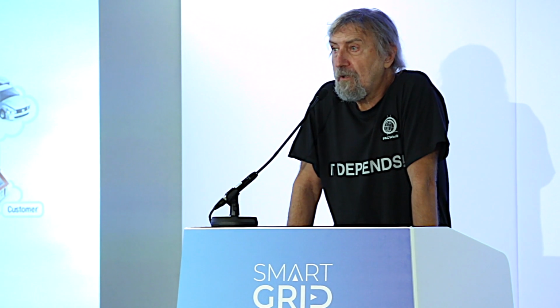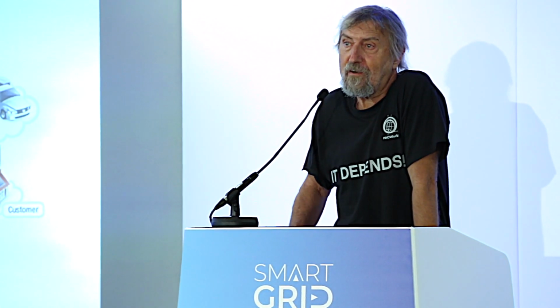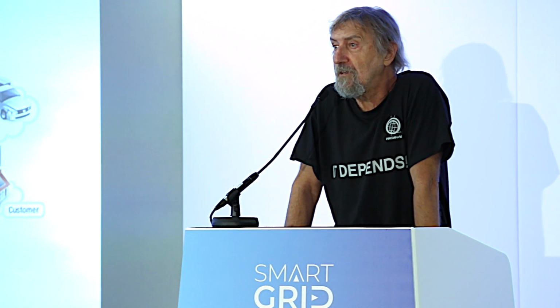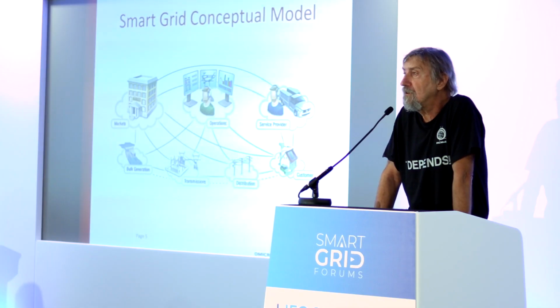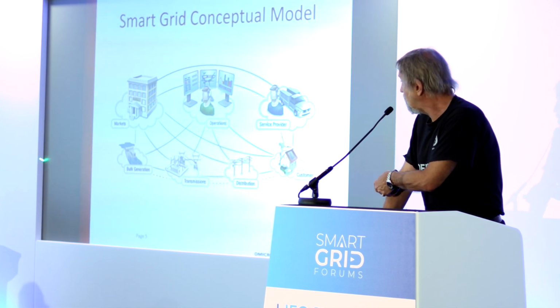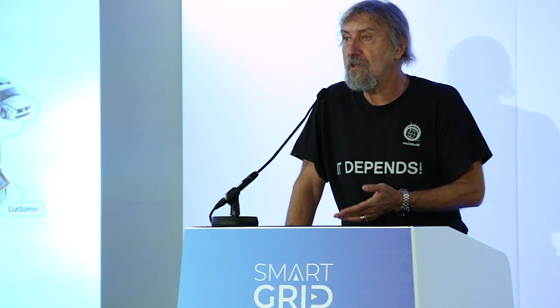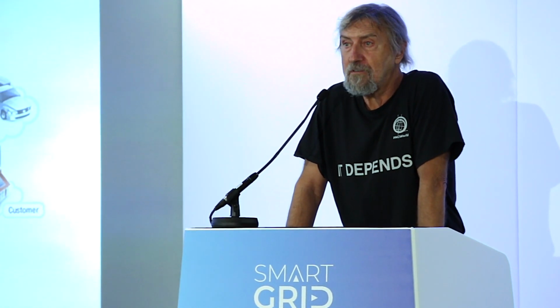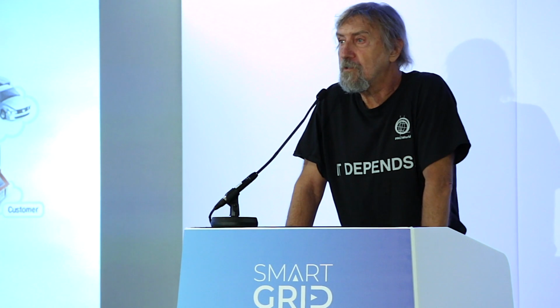Then, when I moved to the US, what was different is that the customers were more sensitive to the interruptions because the characteristics of the load have changed, and we were starting to talk about power quality. So power quality was one of the driving forces on top of the stability of the electric power system. But still, we knew how the system behaves because all these bulk generators were synchronous machines, and we knew how to model the synchronous machines. We knew how to do dynamic stability studies. We knew how to determine what is the fault clearing time that is critical for the stability of the electric power system. And the distribution system was still radial, so the protection was also still simple.